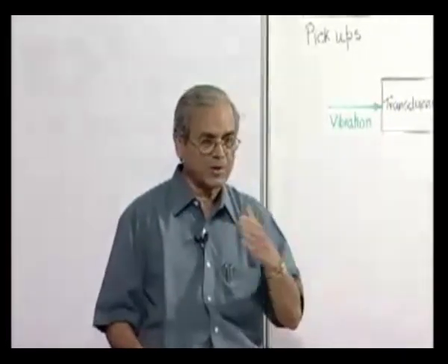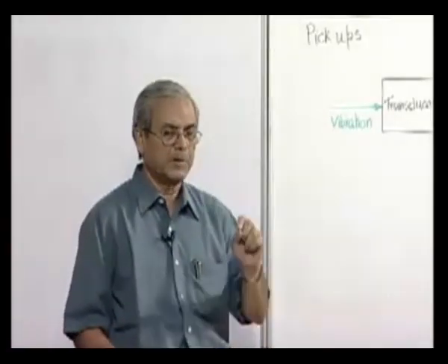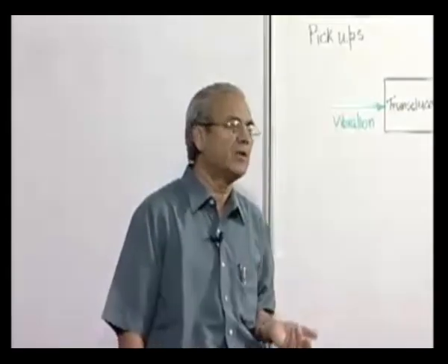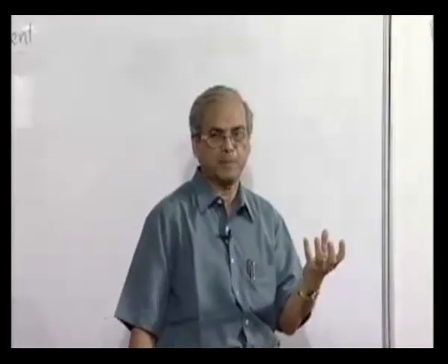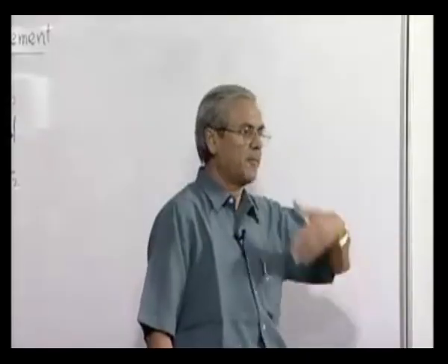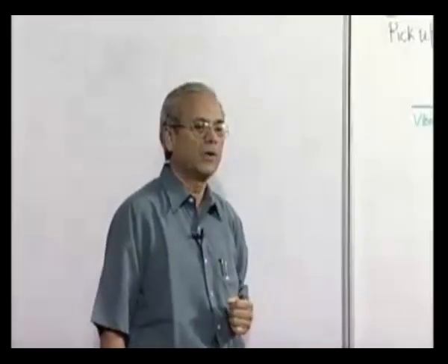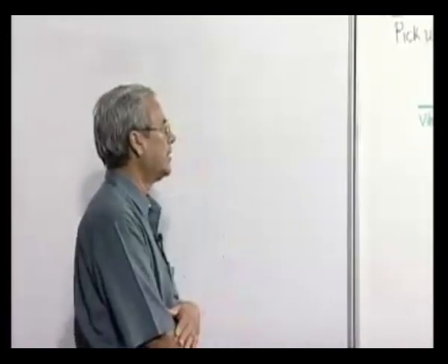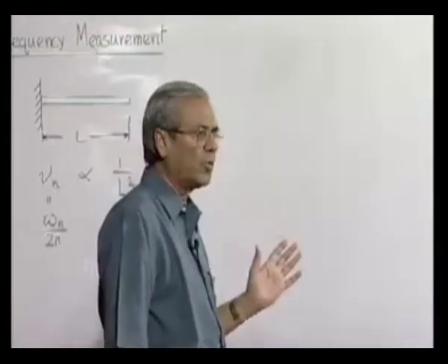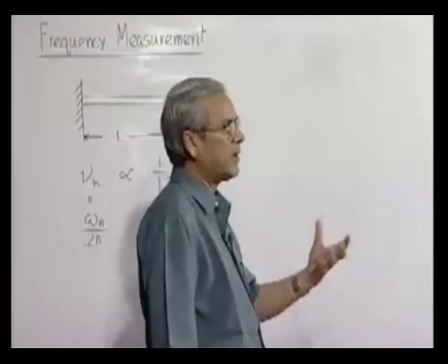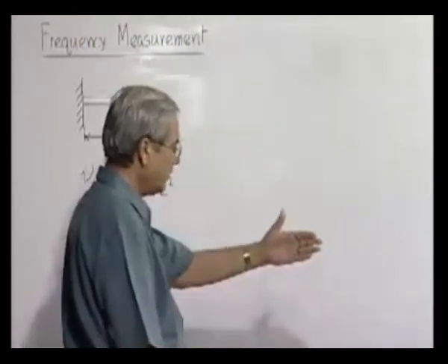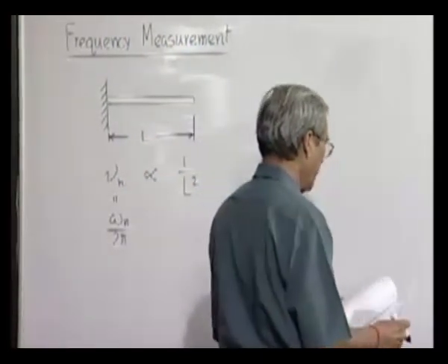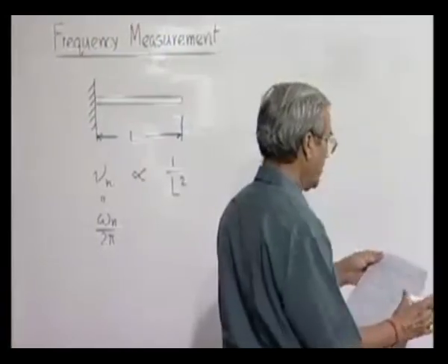It is not very accurate because by visual observation it may not always be possible to say when the amplitude of vibration is maximum, but it can be easily augmented by attaching a simple electric pickup signal which gives the vibrational amplitude, and measuring the amplitude by some meter or by some oscilloscope we can make a better estimate. But in a crude way, since the objective is to get some idea about the order of magnitude of the frequency, visual observation is enough. So this vibration pickup, called the Westinghouse vibrometer, is like this.